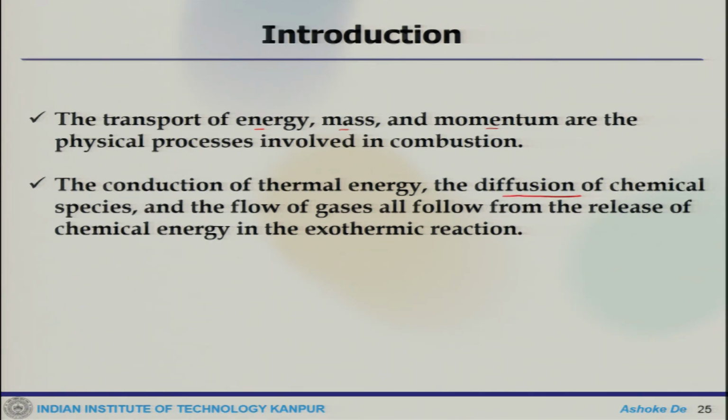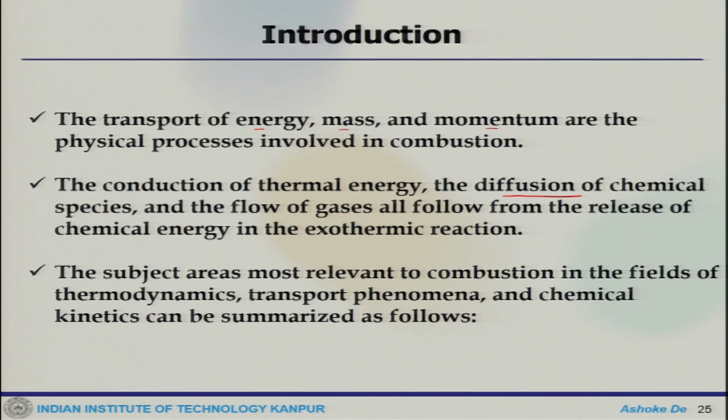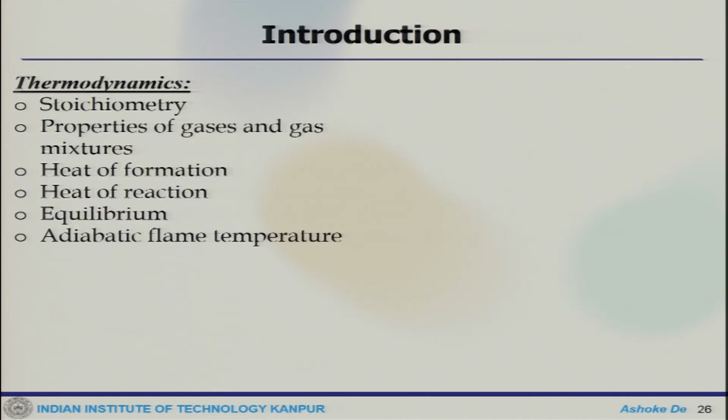It is because of the interaction of the different species at the molecular level that the reaction is allowed to take place and evolve, and then the flow of the gases all follows from the release of chemical energy in the exothermic reaction. So, the things which are mostly relevant in combustion, one very important is thermodynamics, and transport phenomena. Transport phenomena means your momentum transport, species transport, mass transport, and kinetics, and one can summarize some of these.